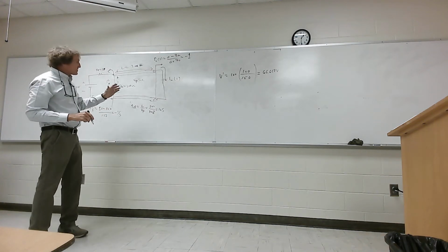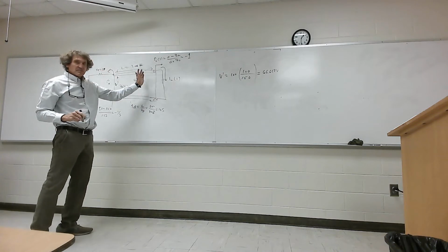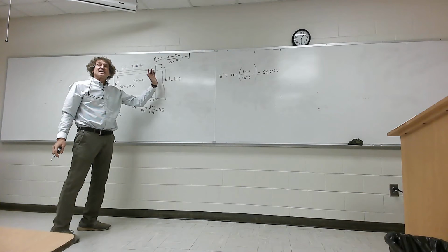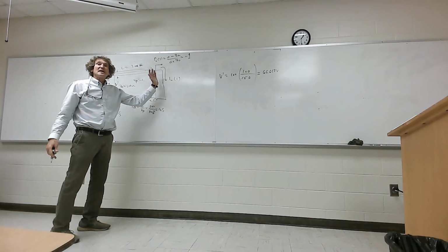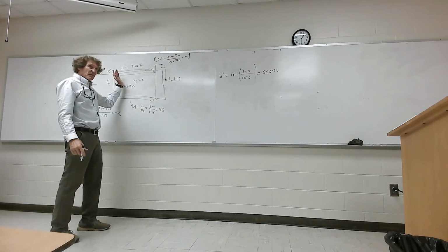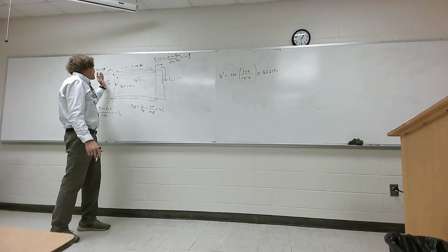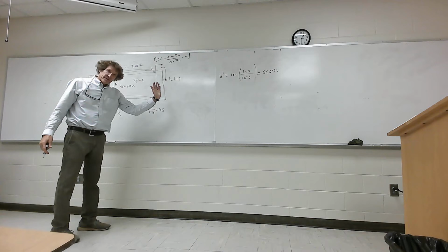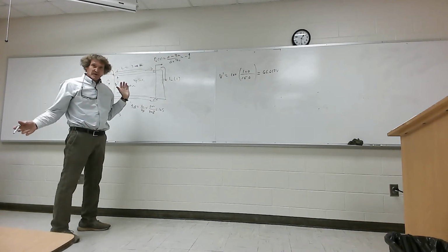Well, you know that when this voltage waveform hits here, I'm just going to talk my way through this one. It's going to hit, and the reflected wave will be the exact same magnitude, only a negative value coming back. Do y'all follow me? Then it hits the source, times the reflection coefficient, comes back, whacks it, and then the negative waveform would go. We can talk about that.